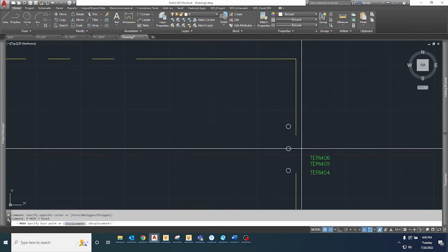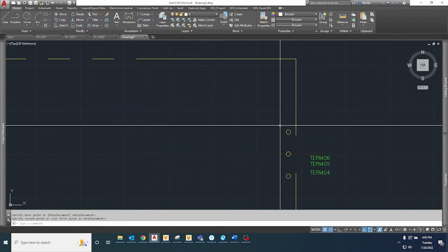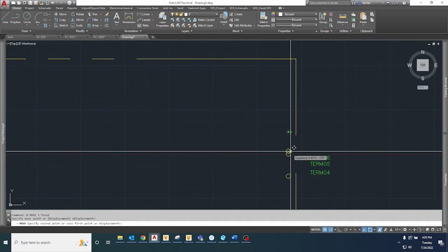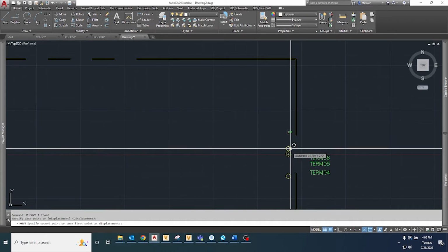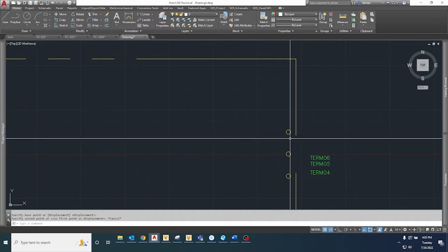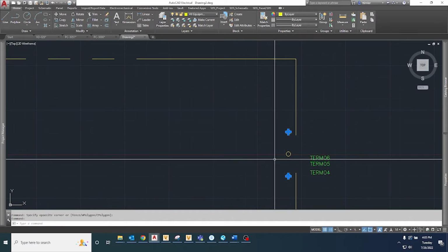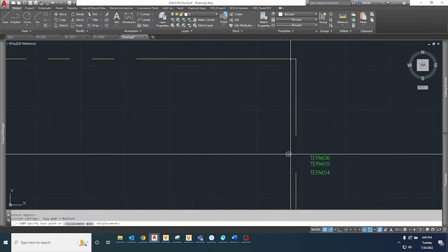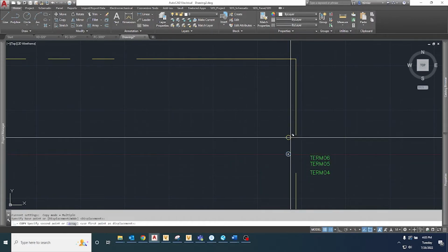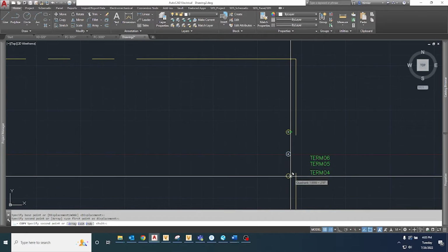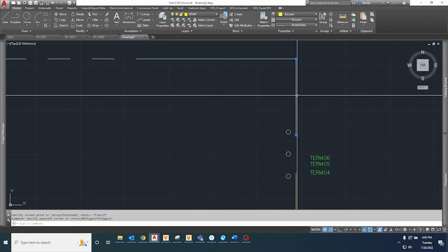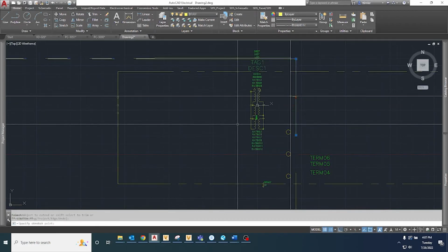Again, grid spacing is something you don't have to use in this situation, but I personally do recommend it. And if you do end up using grid spacing, I would also recommend using the same grid snap settings between your schematic drawings as you do your symbol files. So I'm going to position these bushing terminals out about a 1/2-inch apart and reconfigure the device box.